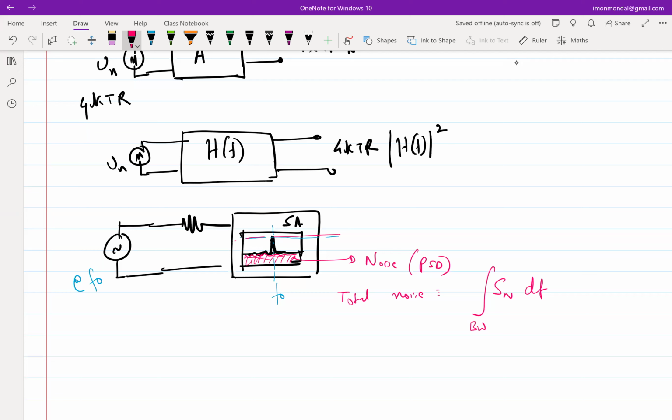So there is a direct trade-off between how fast your communication can be with respect to how noisy it is, right? So when you are trying to send information over a very noisy channel, or you expect the signal arriving to you will have very low strength, and there is nothing you can do about that strength, then it's better to have a very narrow channel. The signal will eventually arrive, and you'll be able to distinguish it.